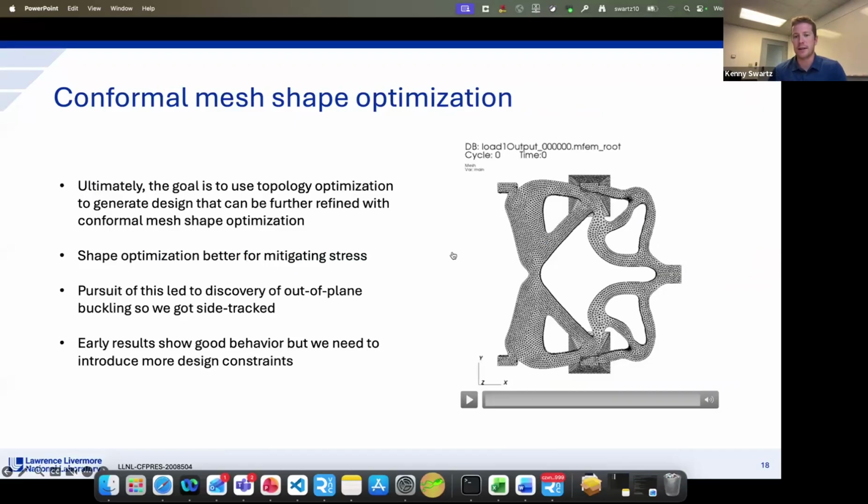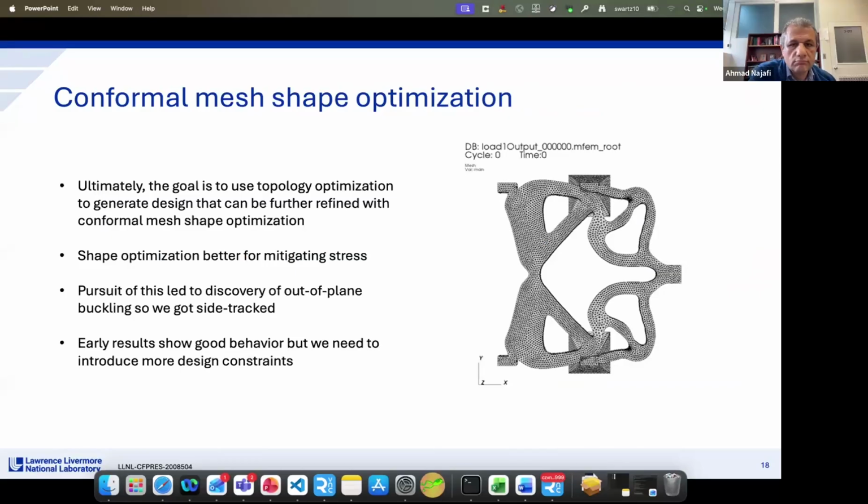And so there's a couple ways you can handle that, right? You can just avoid the contact. You could write constraints that make sure that the design doesn't hit itself, just by looking at the geometry. Or you could model it. I think we would like to eventually model it. But differentiable contact is a hard thing, and we're not quite at being able to put that in the optimization today.